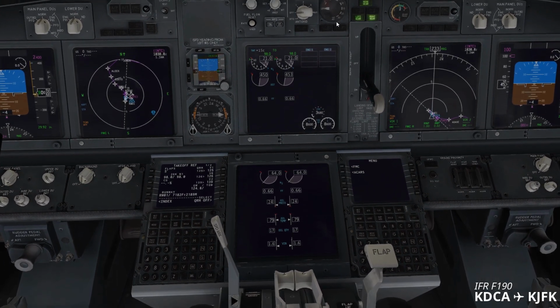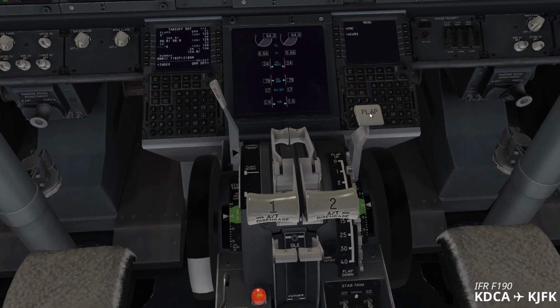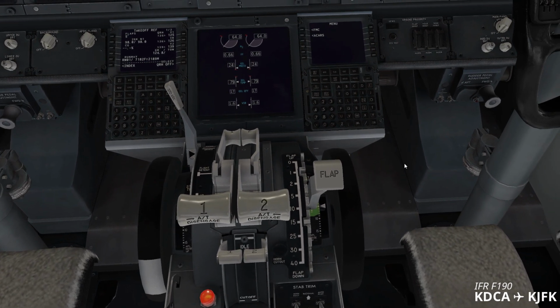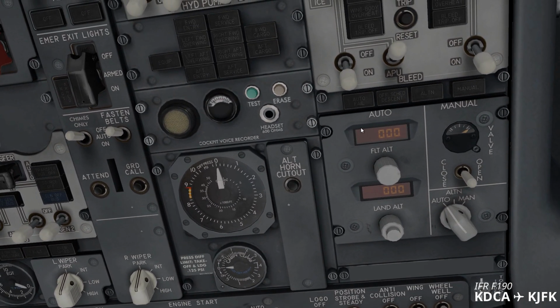And before we forget, we chose the flap 5 degrees, so let's go ahead and put the flaps in so we don't forget. And you also want to set the pressurization system of the aircraft, so you need to put in there like 19,000. That's how high we're going. Otherwise people will run out of oxygen and it won't be fun. And turn on the bleed. That is all it's needed.